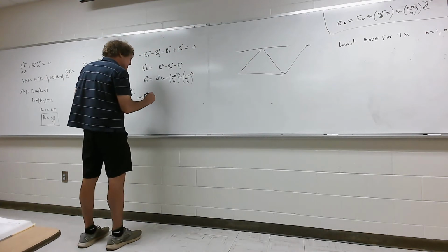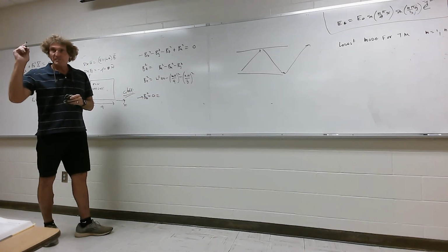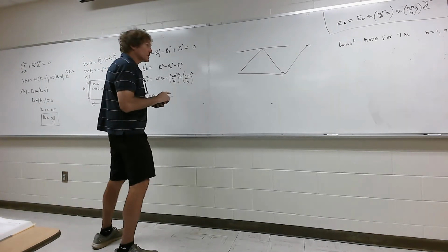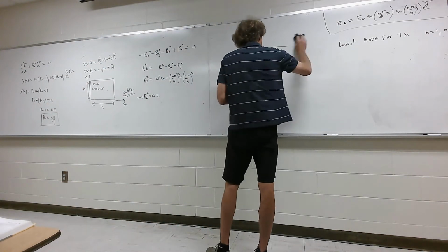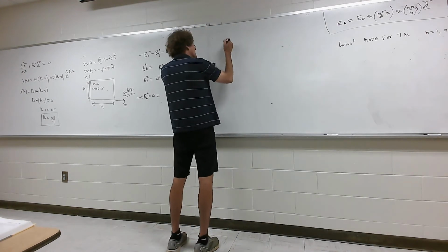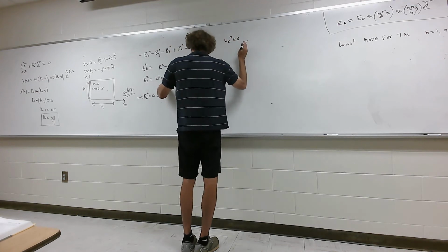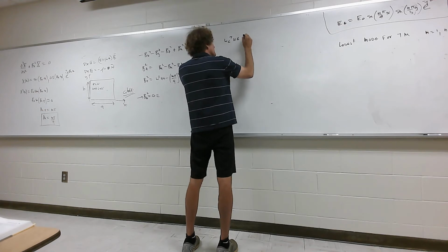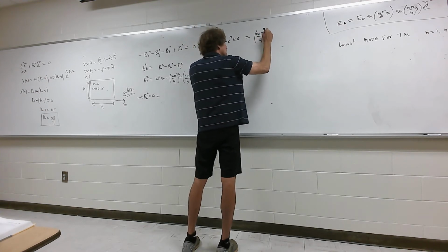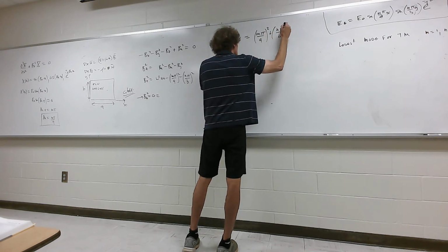When beta z equals 0, now we have omega squared mu epsilon. We call it omega sub c. That's the cutoff radian frequency. And I'll put it over here. So now I get omega c squared mu epsilon, and I'm going to set it equal to m pi over a squared plus n pi over b squared.